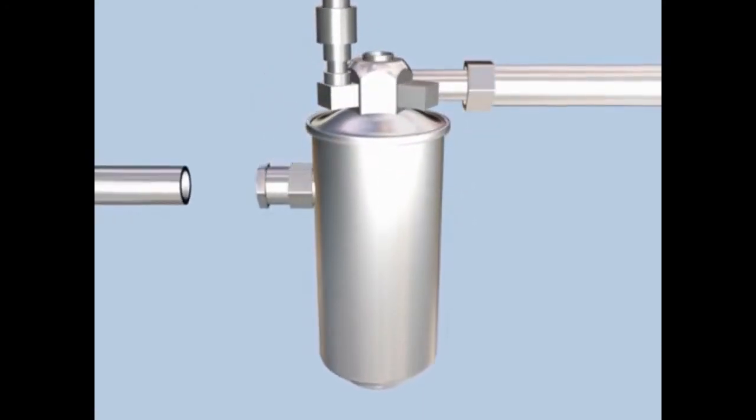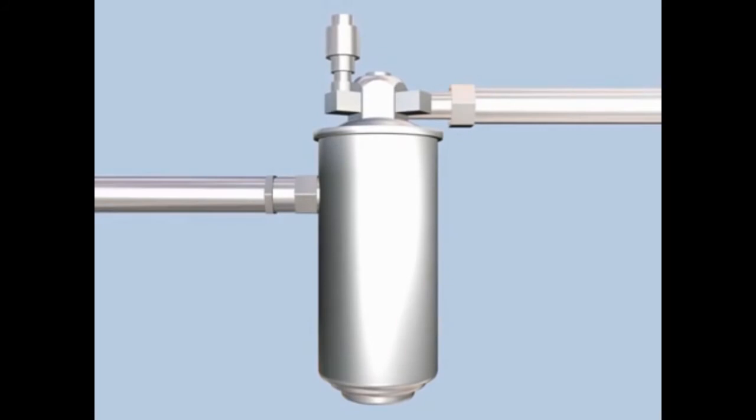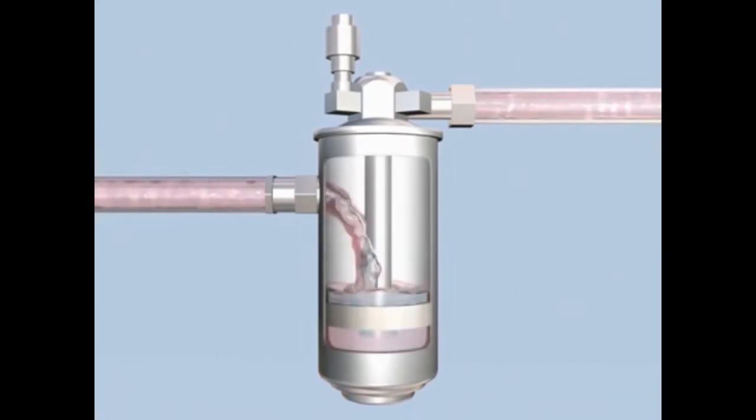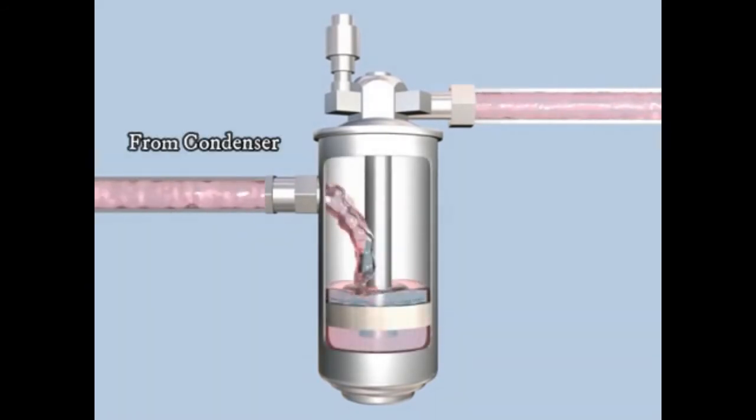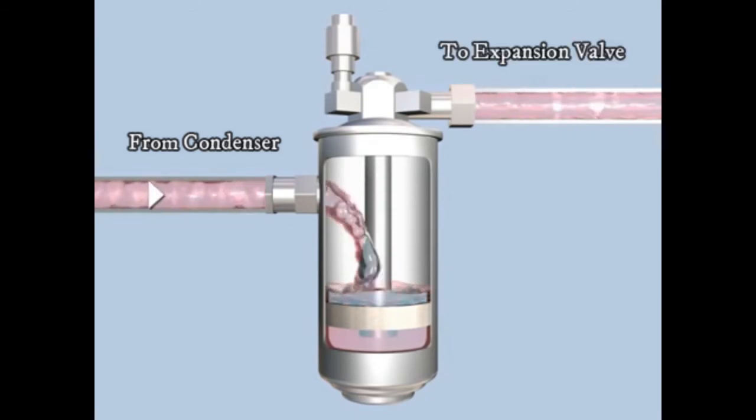Liquid receiver. Refrigeration systems provided with an expansion valve are often equipped with a liquid receiver, built to withstand high pressures. The functions of the liquid receiver are: 1. Separating the refrigerant vapor, to prevent its transmission to the liquid line. 2. Receiving the liquid refrigerant from the condenser through a drip tube, it pulls the liquid from near the bottom, and towards the expansion valve. 3. Stores liquid refrigerant during any maintenance shutdown.